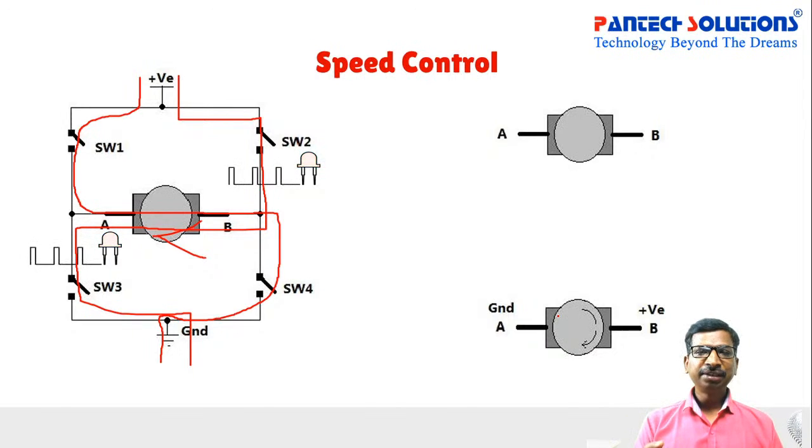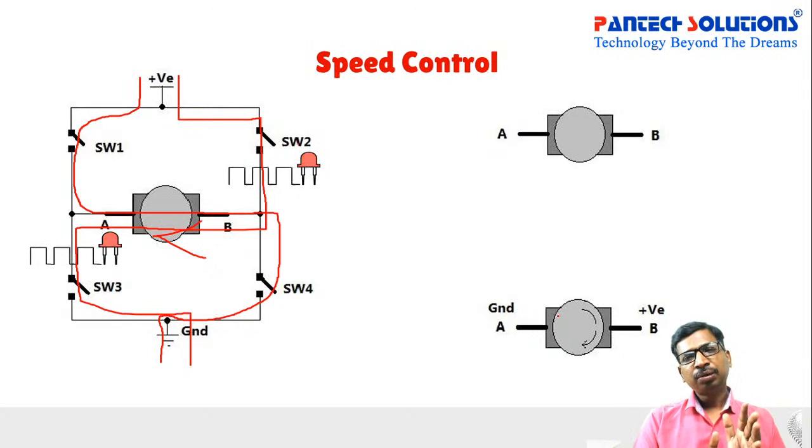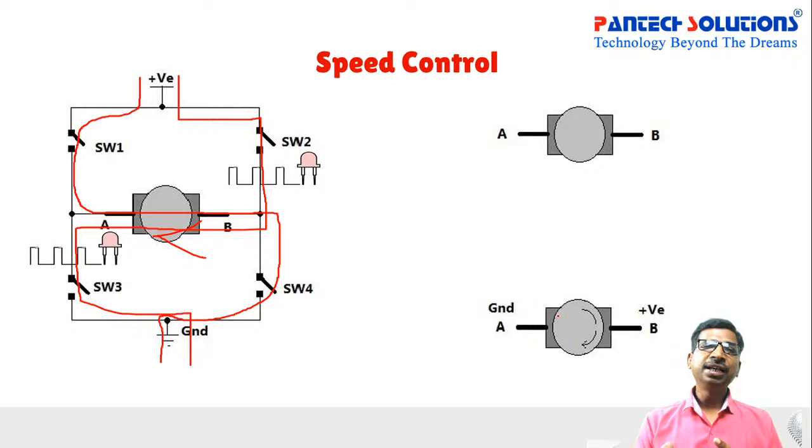Starting the machine, if you initially apply the entire voltage, that voltage will disturb the entire magnetic system inside the machine. In that condition, a transient period may happen. During that transient time, the current, torque and speed of the entire machine will have transient behaviors.